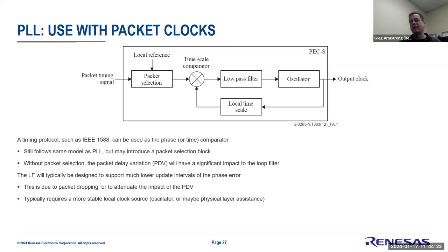And these are being synthesized in like gigahertz or even tens of gigahertz. You can't synthesize this using some sort of simple FPGA or digital circuit to try to synthesize a digital clock rising and falling 10 billion times a second with very precise, clean edges coming out of that clock. So PLLs are very commonly used still, even with packet-based clock distributions.